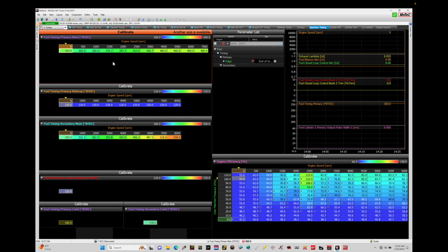Now, the fuel injection timing is important because if we don't have it optimized and timed correctly for the engine we're working with and the location of the injectors, we'll find that we need more fuel flow within a transient type of condition, meaning we have to increase our injector pulse width more than we would otherwise if the injection timing has been optimized for our engine. So injection timing is important, and we need to have taken care of that before we even jump into fuel film tuning.